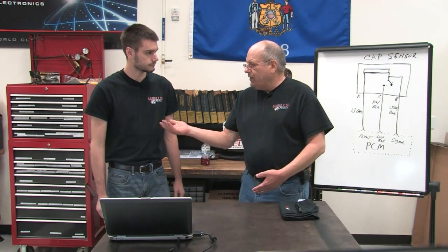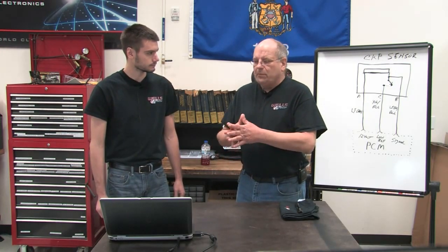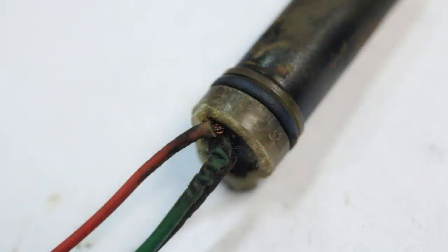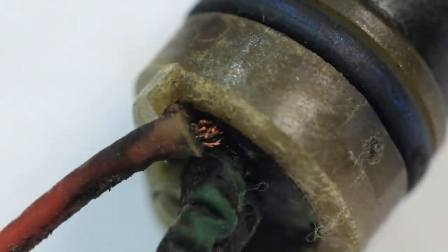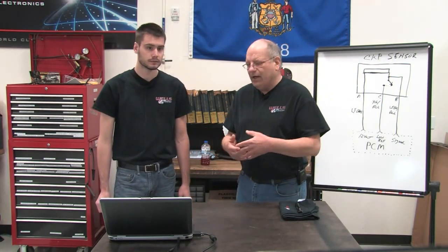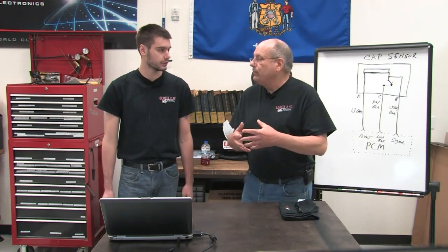You know, and then like you said, those wires. Let's bring up that picture of the cam sensor. And you can see where these wires were shorted out. Okay. So now you have a short. Did we affect how that PCM is actually functioning? Did that overload the driver or something in there? I don't know.